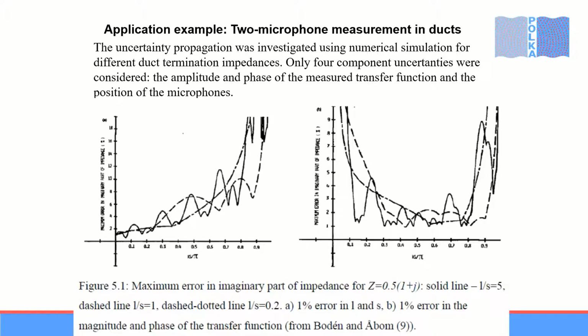So that's at the right end of these curves. And at the left end, you have the low frequency region, where in the measurements of the frequency response functions, you get large errors in the phase, meaning that the error sensitivity also goes up in this region.